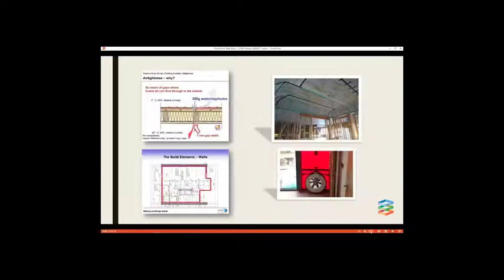So testing air tightness through design is actually important. The red line test, which is an example on the left, is not only tested in plan; the detailing of how that gets built has to be done in section, and any detailed joints have to be thought about. Then all of that gets verified on how well the building is sealed through an air tightness test.